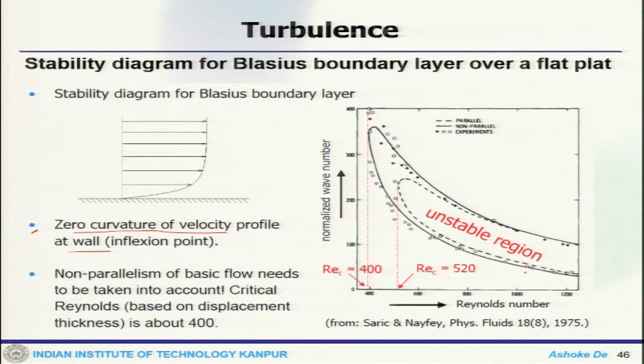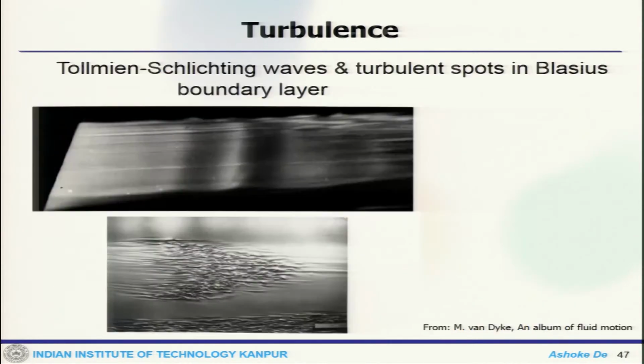So, if you take different flow regimes, whether it is a simple flow between two parallel plates or a boundary layer flow, you can demarcate through linear stability analysis which zone is stable and which is unstable. The Reynolds number at that point would be the critical Reynolds number, which tells you what the situation could be.